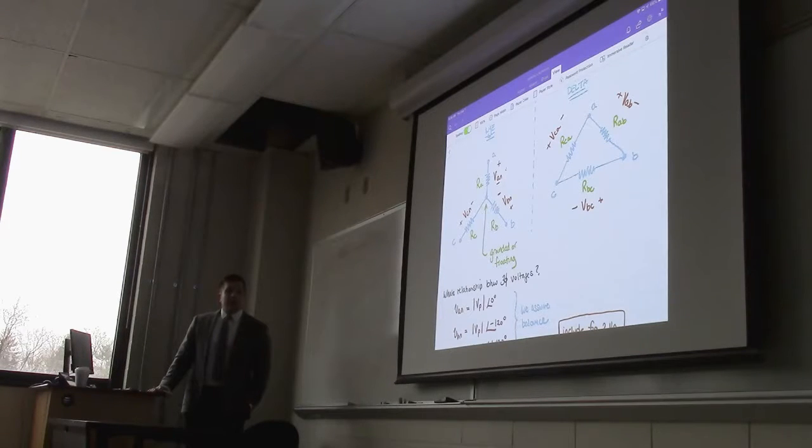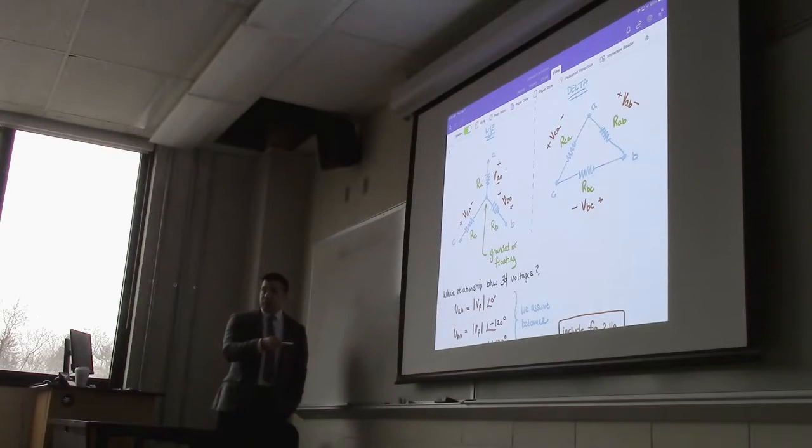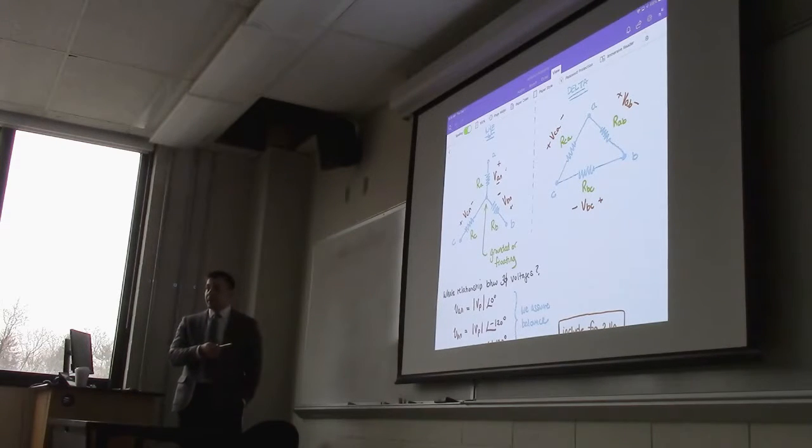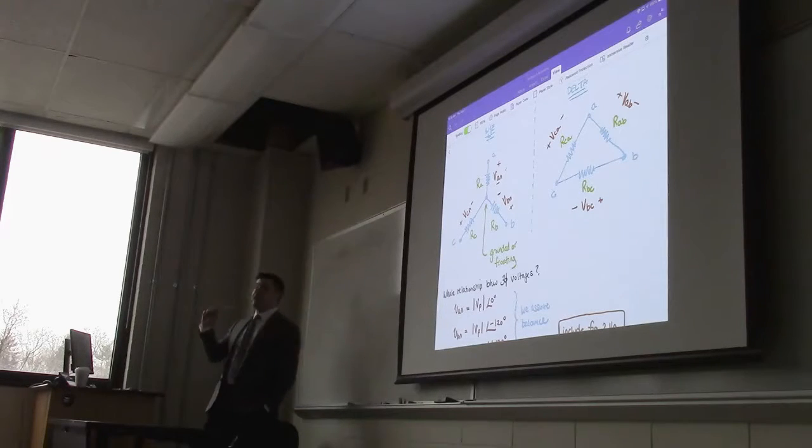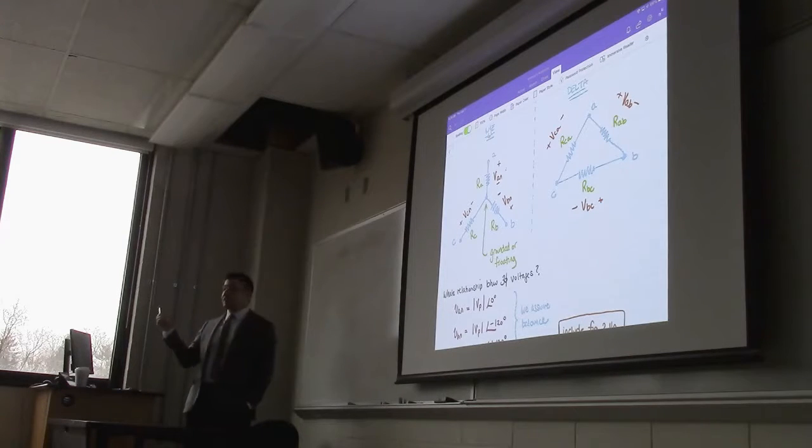Well, the simplest answer is that your socket in the wall is just a single phase anyway. You have only one phase running. The three phases come in, let's say, into TCNJ, and then they get split up, but a single phase may only run to a certain building, or two phases may only run to a certain building, and most definitely a single socket is only one phase.